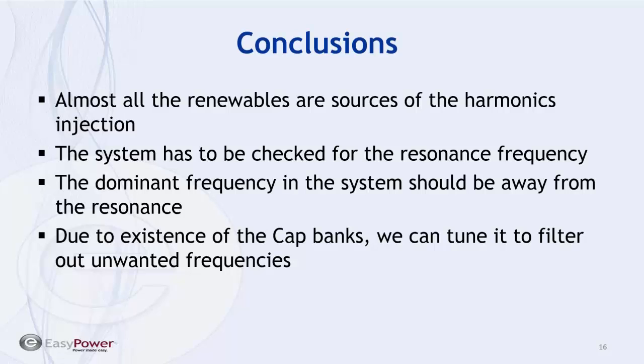harmonic. So we try to get rid of some harmonics, and we try to tune the cap bank to filter them out. We have to keep in mind that this is going to change some other poles in the system. So it's worth going back and looking at everything again, making sure that nothing has become worse. It's correct that you filter out some harmonics, but you might actually have shifted some poles around, which might make the situation worse. So you have to revise those numbers too.